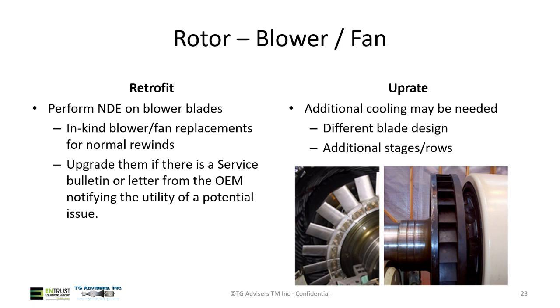So for the rotor, blower, and fan, as always, you're going to want to do your NDE. Anytime you take your component, your blower, apart, you want to NDE it. Replace in kind for a normal rewind. Upgrade if there's a service bulletin or a technical letter from an OEM that's notifying you of a known issue, a potential issue.